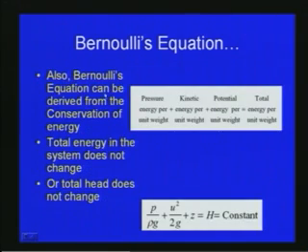So, now, as we have seen, we have derived Bernoulli's equation based upon Euler's equation for the inviscid flow, but Bernoulli's equation can also be derived from the basic Newton's second law, or from the conservation of energy. So, from the conservation of energy for the system which we are considering, as we have seen in this figure,